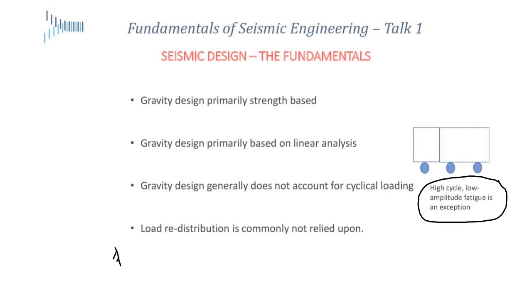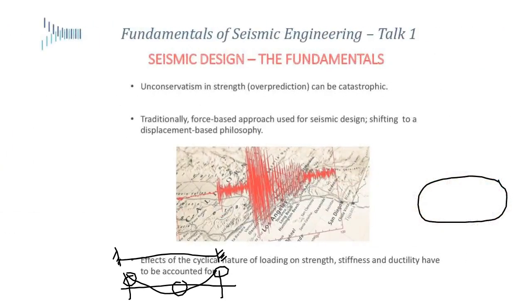So if I have a beam, sorry, this is not being drawn very nicely, but I can come up with the elastic bending demand, which looks like that. And I can just design each portion to the maximum demand that it can take and make sure that I have that much capacity and my design is going to be just fine. Now, when it comes to earthquakes, things are a little bit different. Load redistribution is something we should rely on. And I'll talk about that.